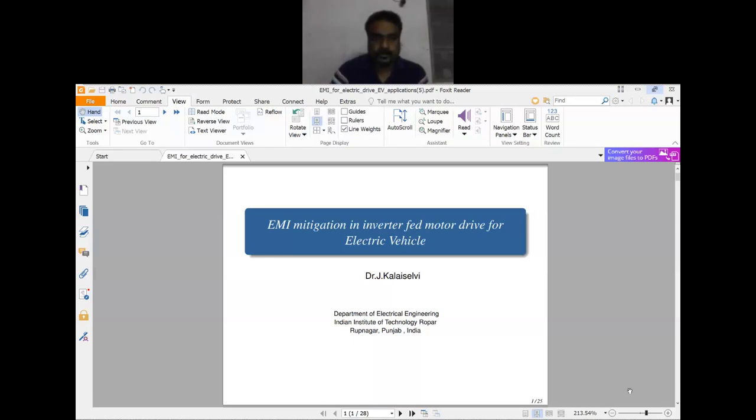After that, the control side has to take care of how to minimize it further. It's not that I have to look at one particular solution to reduce the EMI. I have to look at all the possible sources and all the possible ways to further reduce it. Otherwise it will burden one solution more. Say for example, I am not minimizing my path properly, I am not optimizing my ground paths properly, and then it will add on to your effort on your filter.